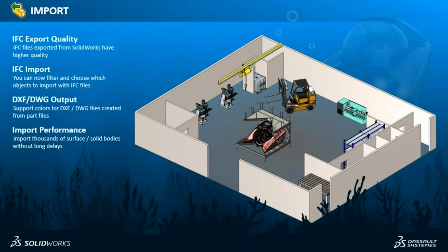So what we have here is called an IFC file format, not new. We just have some options that allow us to leverage that information better than we had in the past. So we can export IFC from SOLIDWORKS, and that gets into those building systems programs if this applies to you. And we can import an IFC file from those building systems. So if you're going to be part of this, what file format do we use? IFC, right? That's usually the standard go-to that all these programs can read and export as.